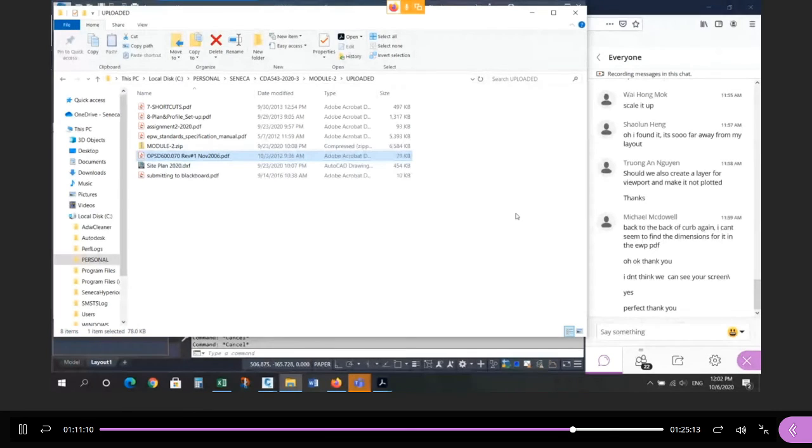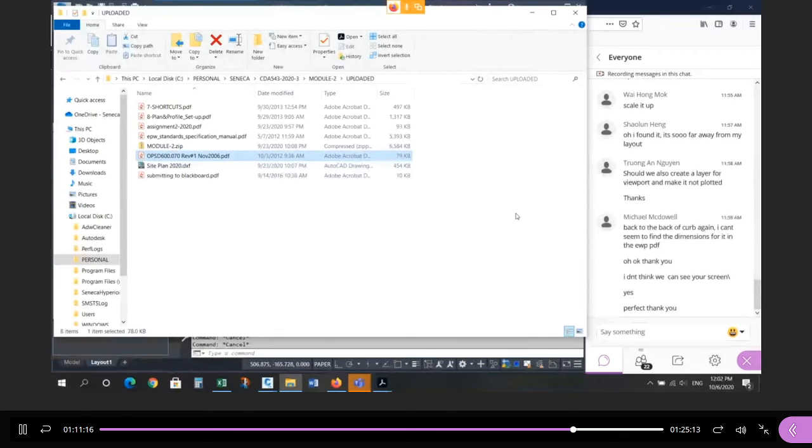So as you look stuff up, keep track of which standards you're using, almost like a reference sheet of what standard you used, right? So what's the width of pavement? In this case, 8.5. How do you know? Because of this standard, right? You have to be able to quote the standard. So it's good record keeping. And then you have a short list of where to look for stuff next time you work in that municipality instead of the whole document.